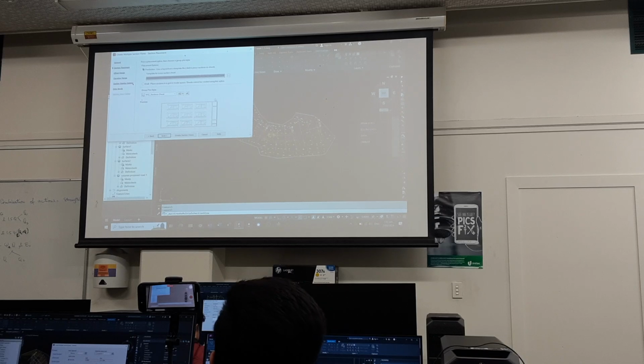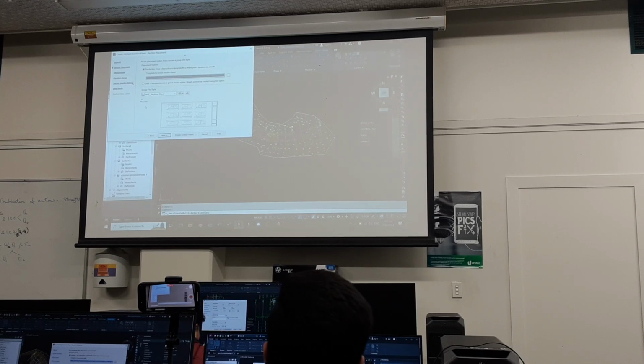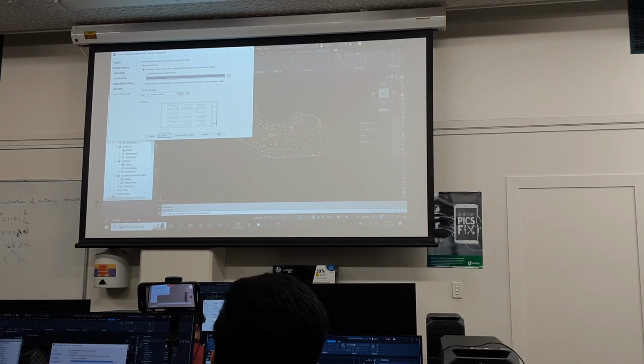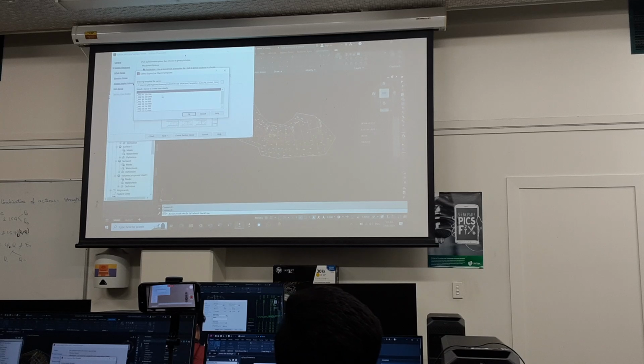And we're looking at it. This is what it's going to do. It's going to produce a Civil 3D title block or sheet layout over the top like that. And we need to double click on the blue dots on the side up here, and it'll give us some ANZ options. This is why it's so critical to load the ANZ.